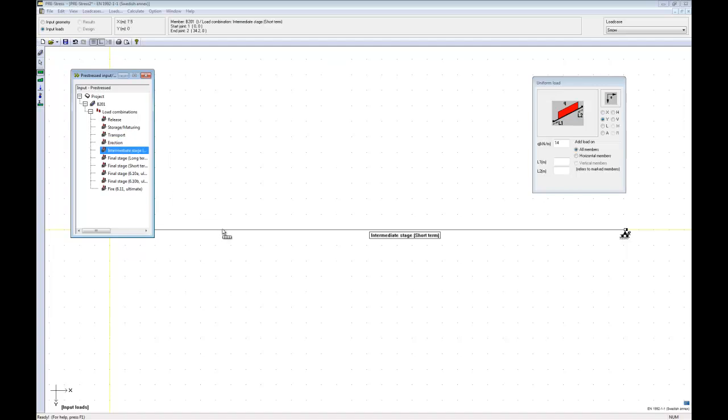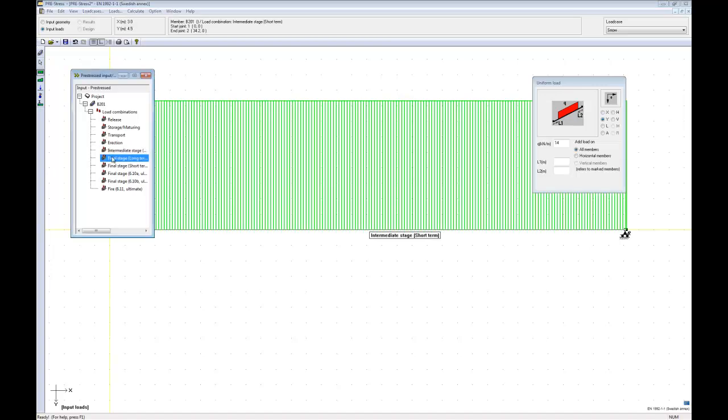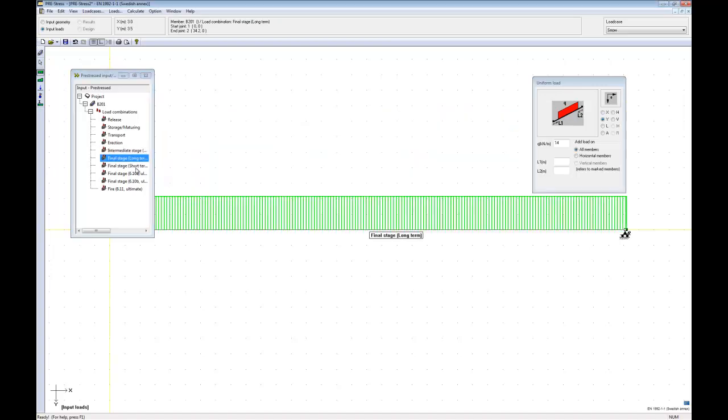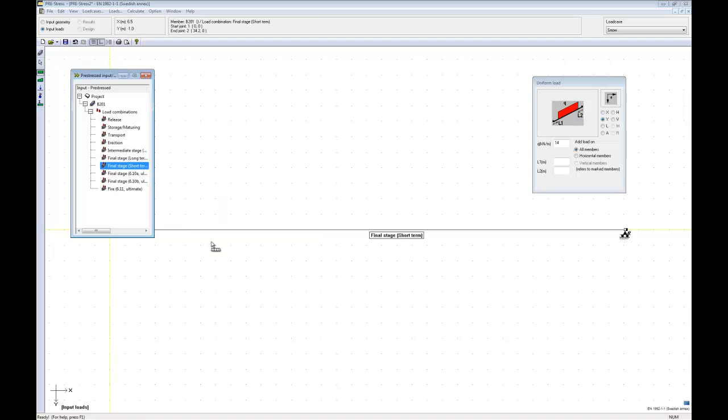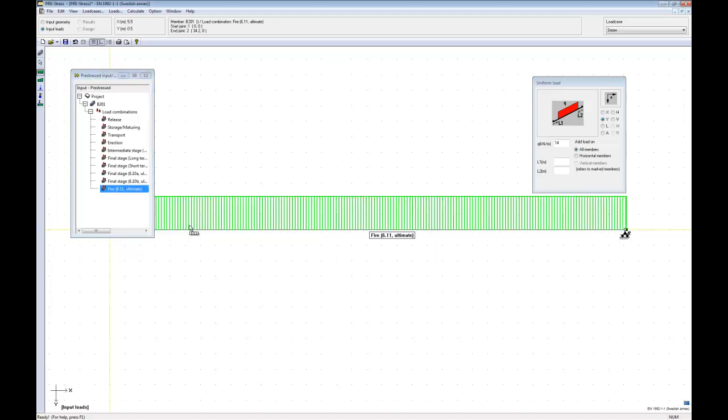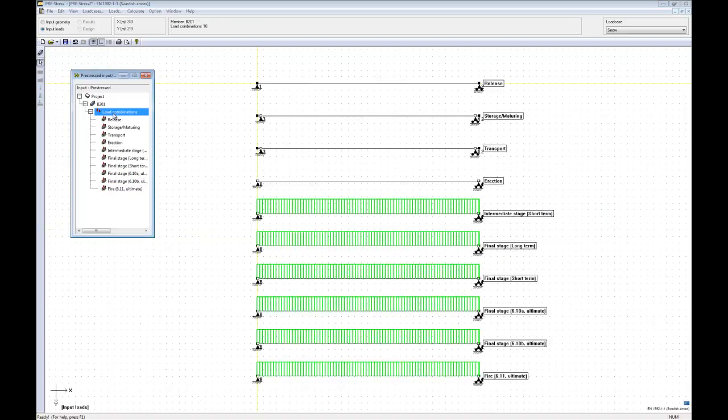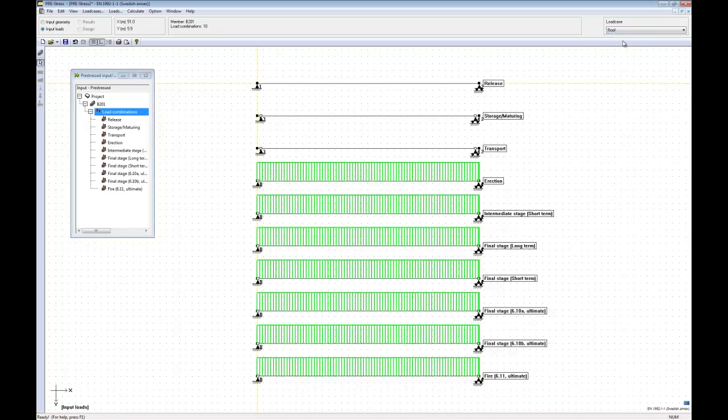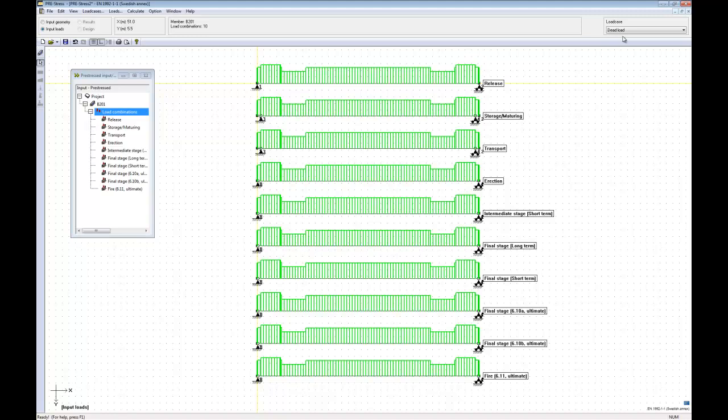off and so on. But when the construction is working afterwards in the maintenance phase, then I will just add the snow load here, and I just add it as a characteristic load here as well. So I have an overview of the snow load, the roof, and the dead load.